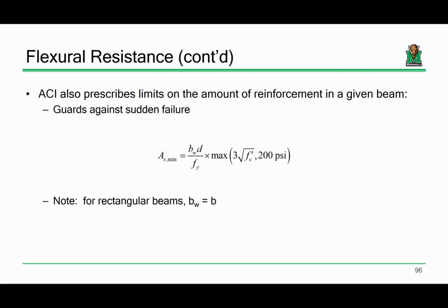In other words, you'll compute a minimum area of steel of, let's make up a number, an AS-min of 1.2 square inches. That's what ACI is saying is the minimum, but you end up providing like 3 or 4 times that amount. Usually in design scenarios, this ends up not being that big of a deal, but you do still need to check it, okay?